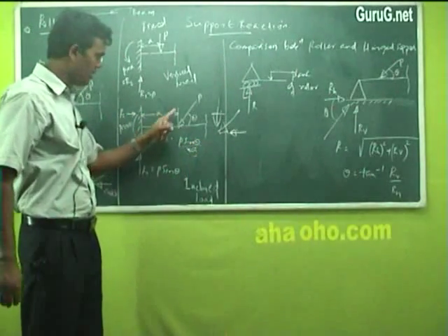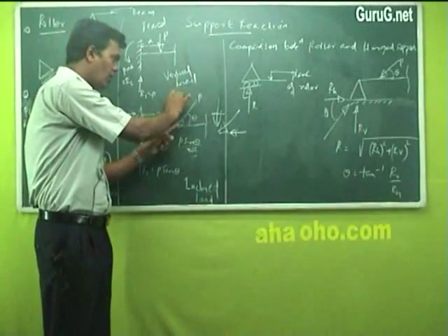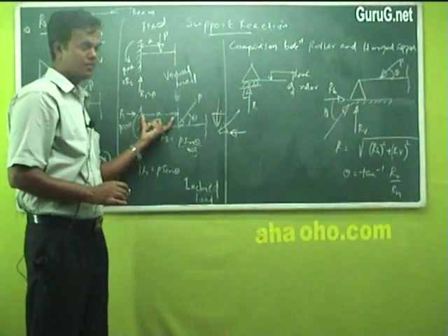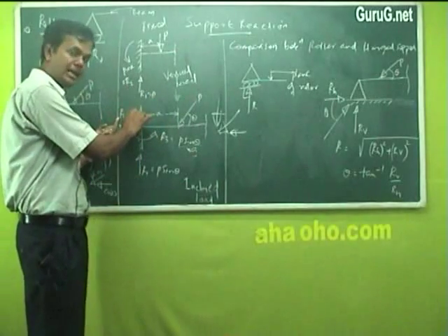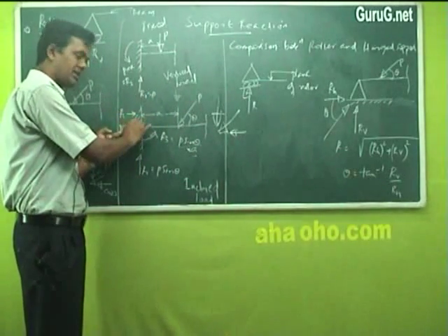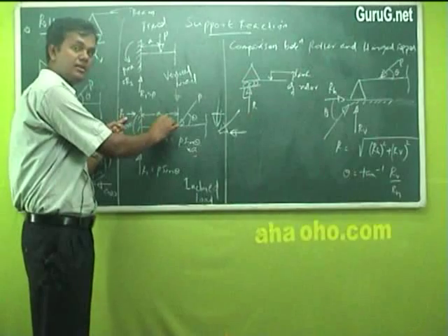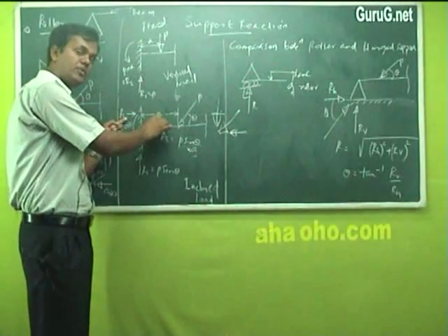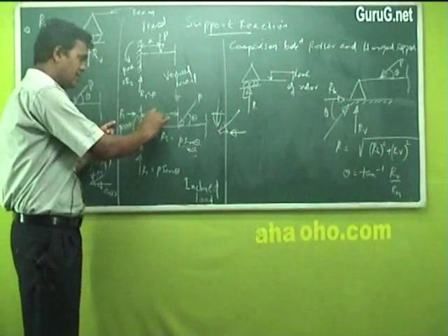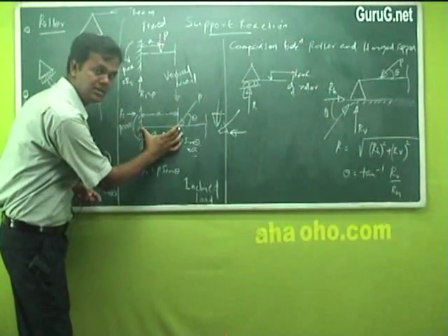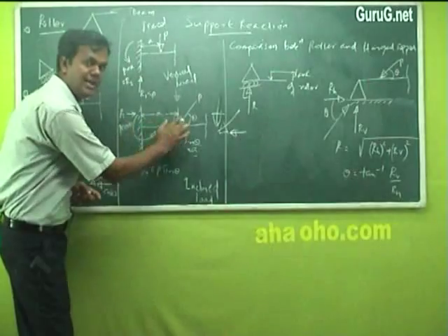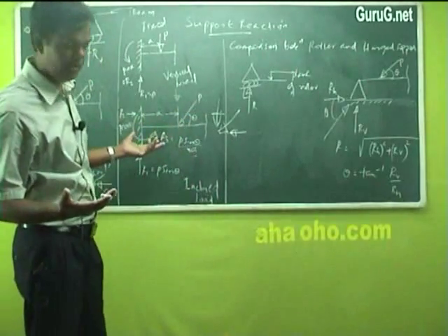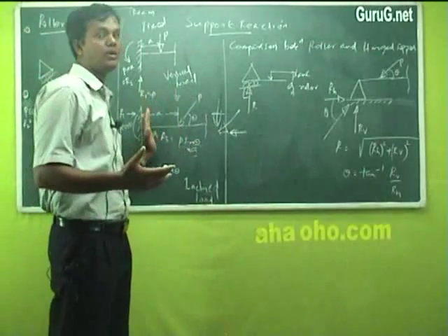Why is that so? We need the load in the vertical direction into the perpendicular distance. Because for the horizontal reaction, R2 is P cos theta, this cannot be multiplied with this distance, because the moment is the load applied into the perpendicular distance, which is what we want. But what about this one here? The distance A is in this direction, and the load applied is horizontal. Both will have the same line of action, so there is no moment there. The moment is only for the applied load into the perpendicular distance.